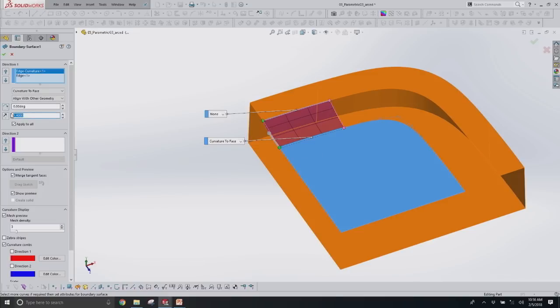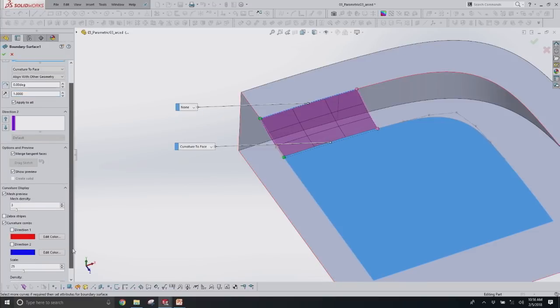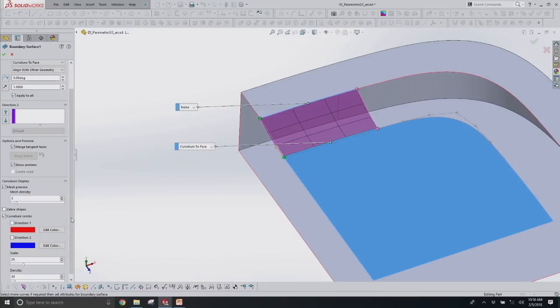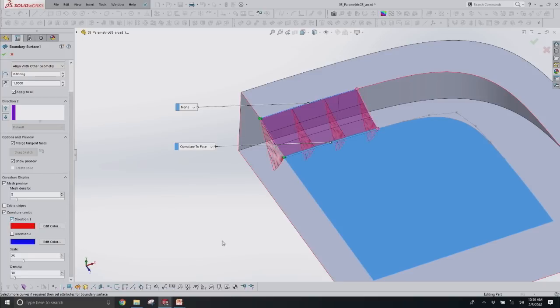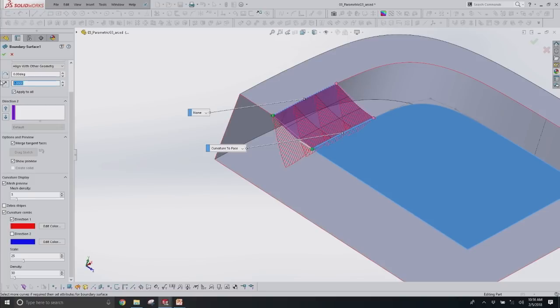One thing to note is, remember when I said that the curvature continuous connections need to look a little bigger, that 40% kind of factor? Out of the box, if we turn on the curvature combs to show us what that default 1 value, tangent direction is what SOLIDWORKS calls it, I just kind of call it the inflate button, because here we can see a big spike in the curvature. We want that to gradually accelerate, and I found that 1.4 is kind of the sweet spot.